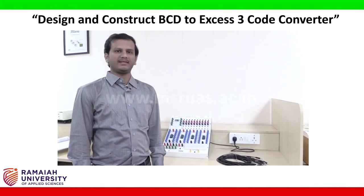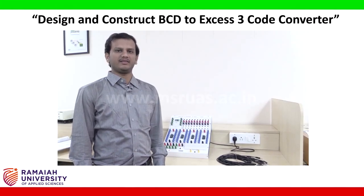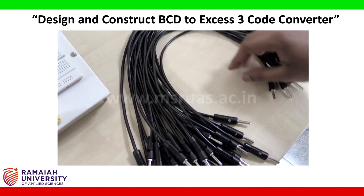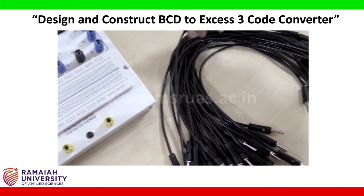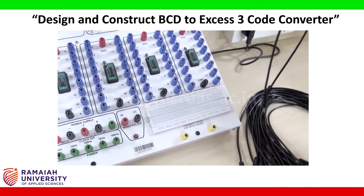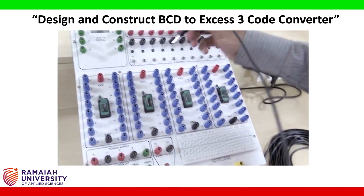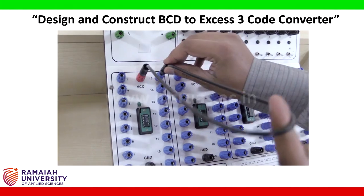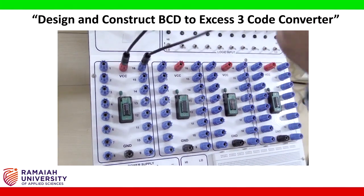Now let us start connecting the circuit as per the logic diagram. Before connecting the circuit, I will connect all VCC and grounds for every IC base. There are 4 IC bases. We are using all 4.